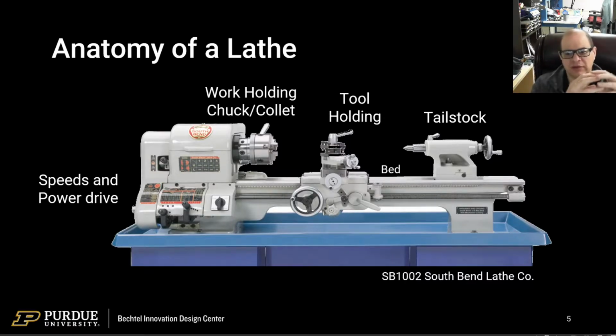As soon as that bar gets quite long and you're spinning it quite fast, I'm sure you can understand that the bar has a real incentive to go off-center. And I'm sure you know how centrifugal force works. The more off-center the bar goes, the stronger the force that bends it off-center is. So one of the classic ways, sadly, to get hurt using a lathe is a long unsupported bar. Because as soon as it becomes a little off-center, it will go very off-center very quickly, and if it hits the bed or hits the operator, it's a very bad situation.